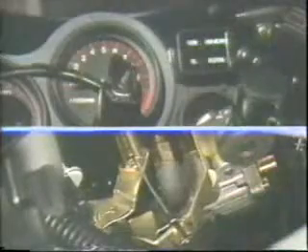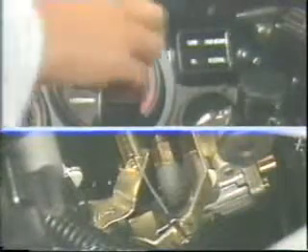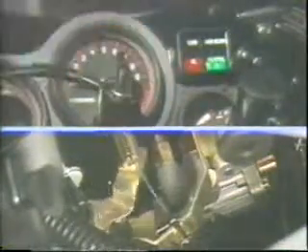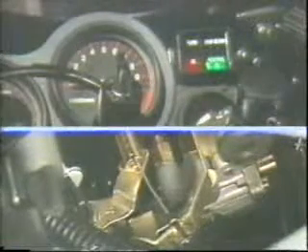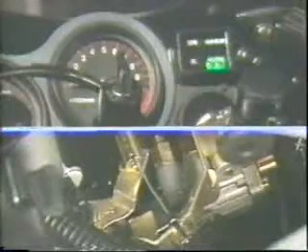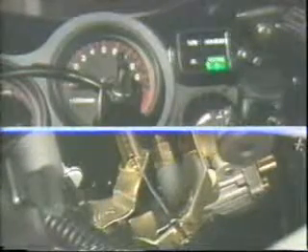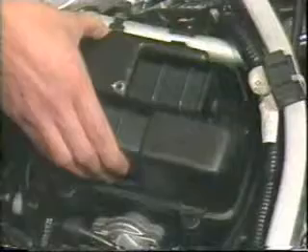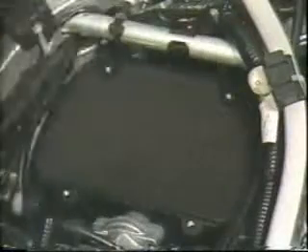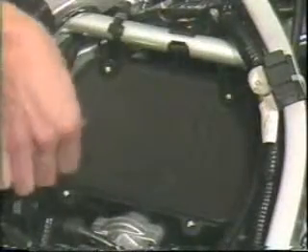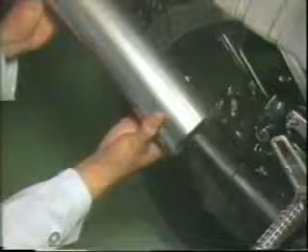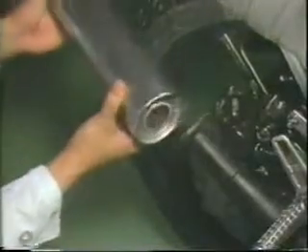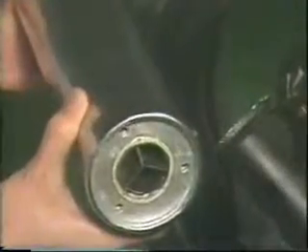The next test concerns the YPVS. Turn on the main switch and see if the YPVS is fully open. At this position, see if the oil pump is half open. If there is no trouble at this test point, you can check the intake and exhaust systems. When you check the intake system, look especially for any dust in the air cleaner. Then look for any excessive carbon deposits in the silencer or the muffler of the exhaust system.